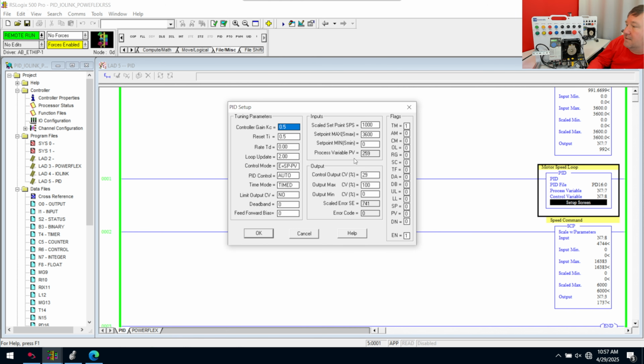All right, that got us a little speed there. Oh, no, it did not. It slowed us down. Let's make that 5. I put it at 0. All right, so that was way too much. So you need to hear the motor screaming at us now. Overshot. Now we're going way down. Now we're going way up. And that's what I see half of your PID is doing.